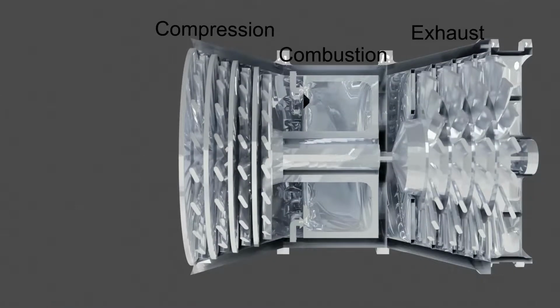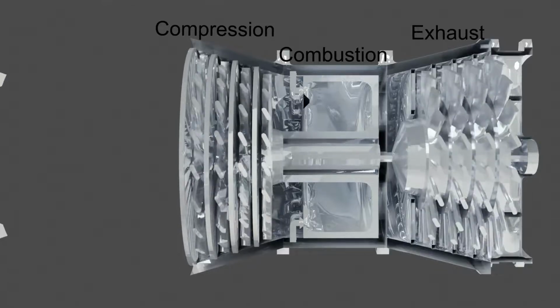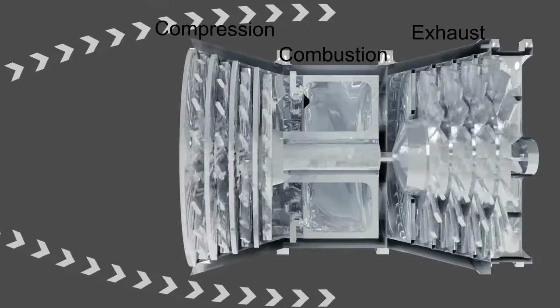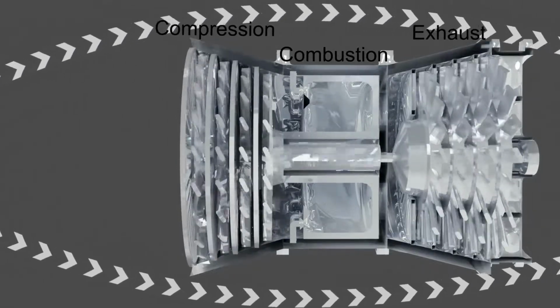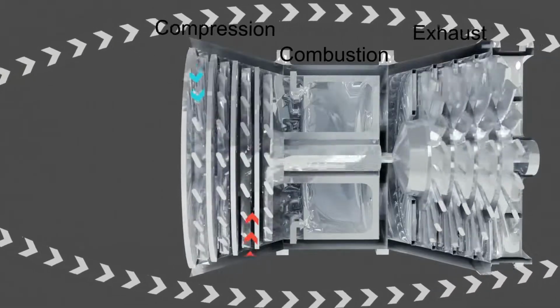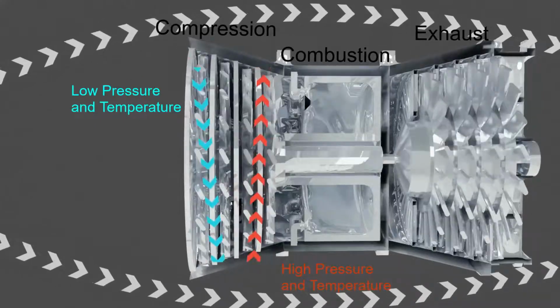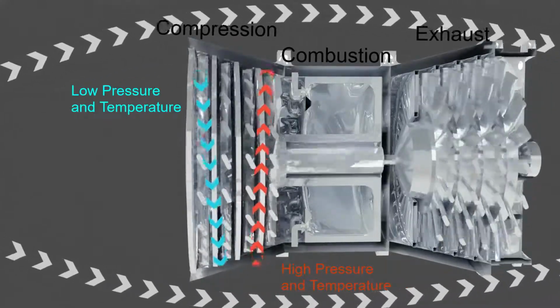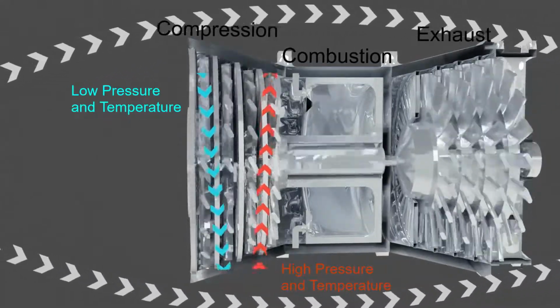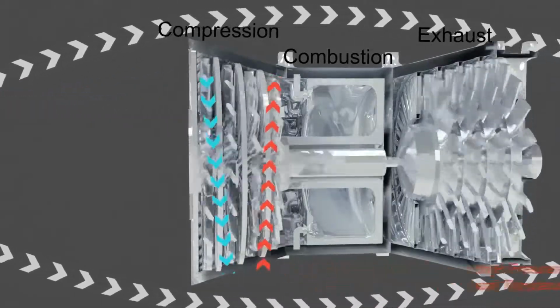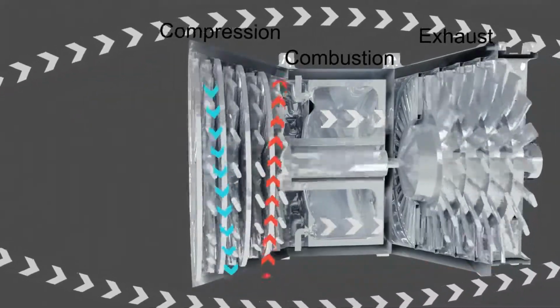There are three main stages within the core. In reality, the proportions of the engine, core and components would be different to this exaggerated model. Initially, air entering the core passes through a series of fans whose radius decreases in proportion to the core. Separate high and low pressure compressors deal with this variation in temperature and pressure. Often they spin in opposing directions for optimal efficiency.